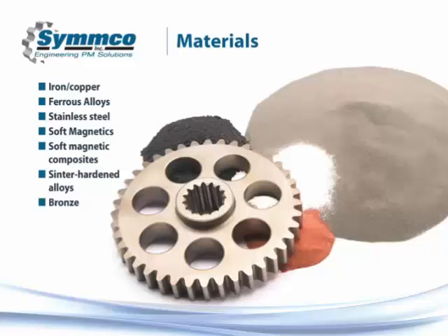One of the new materials that's really rising in the industry is a soft magnetic composite material, an SMC. This is the material that you won't find in the standard, but is used in soft magnetic motor systems to create parts that meet a very high hertz energy input and a very low eddy current demand that the complex motor design would have. So one thing that you won't find in the standards that definitely is available in the industry is those soft magnetic composites.